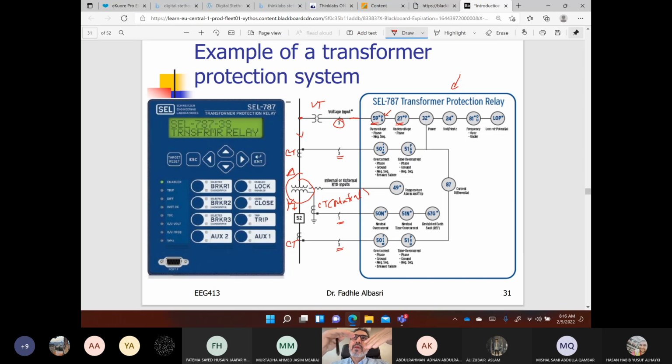So of the voltage quantity, you determine the negative sequence of that voltage, and based on the negative sequence, you decide: is this an overvoltage condition or not? Then this is negative sequence based, and we call it 59Q. Now, if you use the actual voltage, we call it 59P. And this is an overvoltage based on the actual phase voltage quantities.